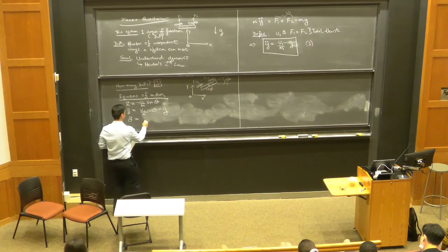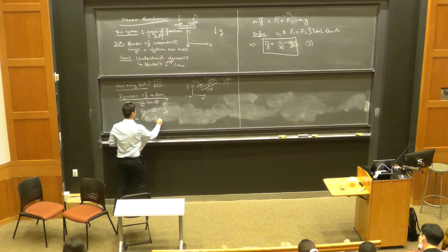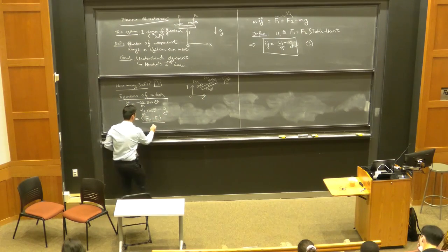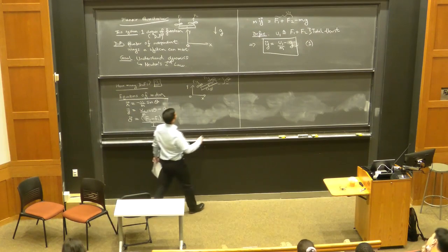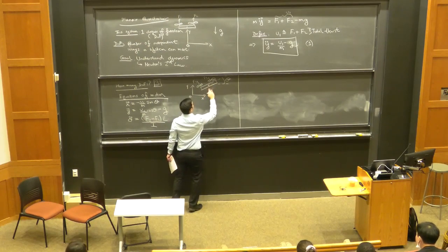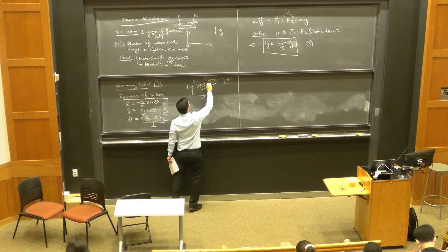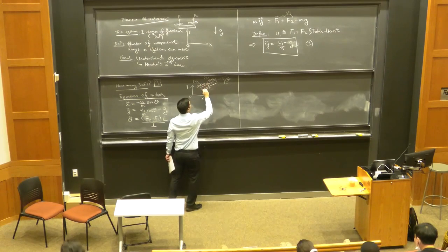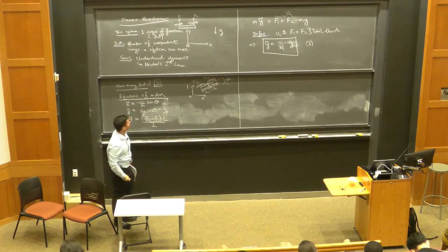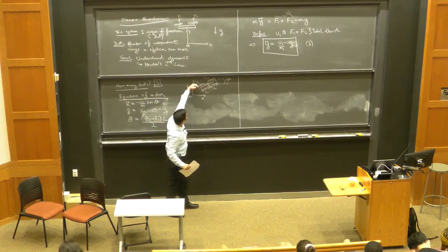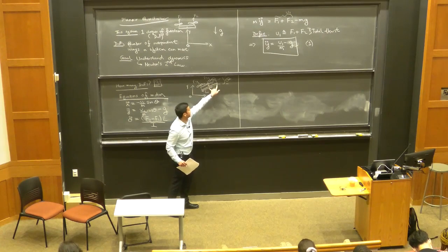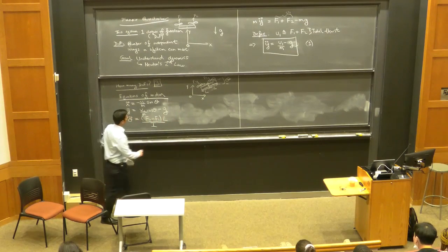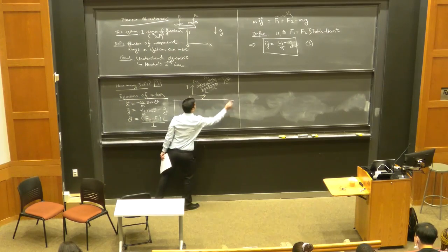And then finally the equation of motion for the orientation. Theta double dot equals F2 minus F1 divided by I, multiplied by L. I and L are quantities that I haven't defined yet, so let me do that. I'm going to move the xy here. 2L is going to be the length of the drone. So from the center of mass to the axis at which the propeller thrust force acts, I'm going to call that L, and then the same thing over here. And I is another physical quantity.